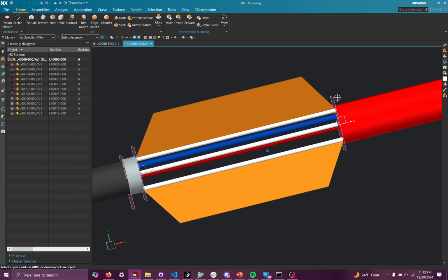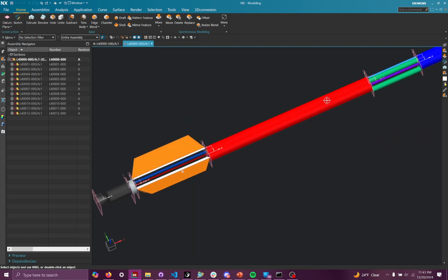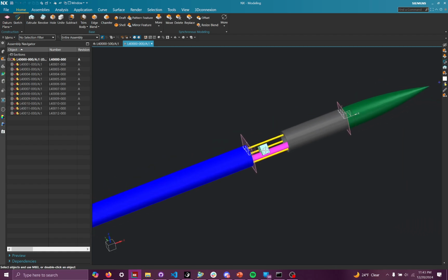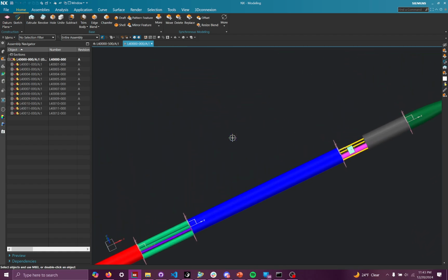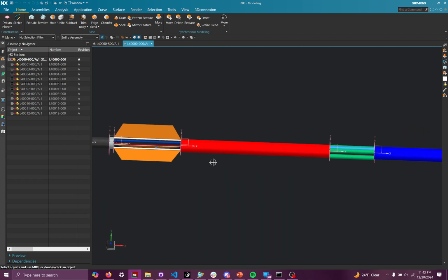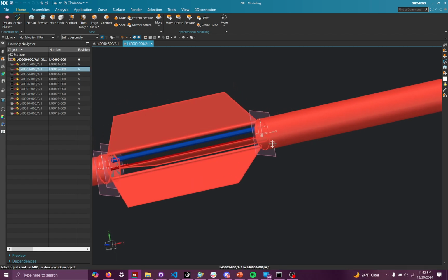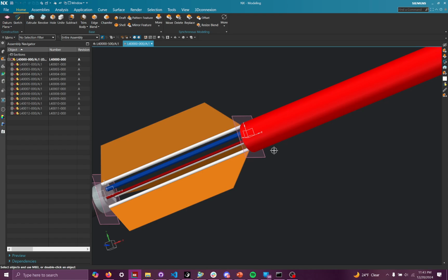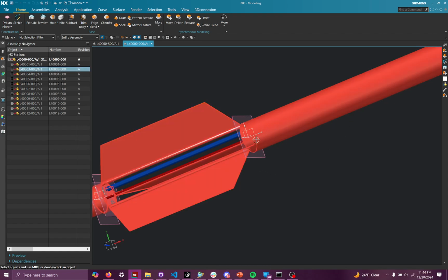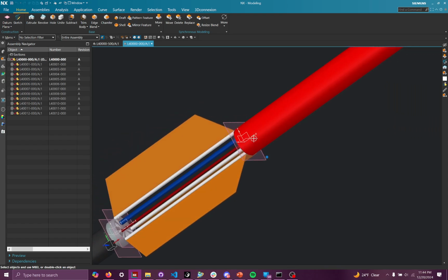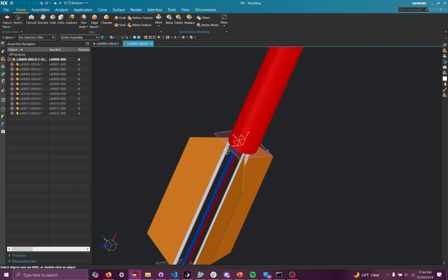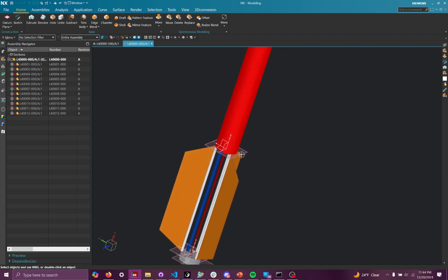So they set the interface locations between different subsystems, and you can go throughout the entire length of the rocket and get a feel for it too. They just divvy up where the rocket subassemblies will be. And then the coordinate systems are also there to provide a reference point for the layout files, so that you have axes to base your revolves around and so forth. They're just kind of there as if you need them to reference off of, you have them. Same with the datums as well.